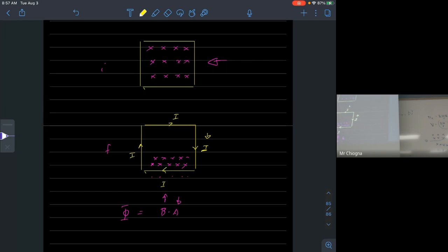So that's the idea. This is the wire. Assume the direction of the current's that way. And then trace out, or just observe, which way the fingers point as you wrap them around the piece of wire. On top, the fingers point in. On the bottom, they point out. Oh, if they were dots instead of X's at the top, you want it to point out. Yeah, let's do that. Let me just erase it.